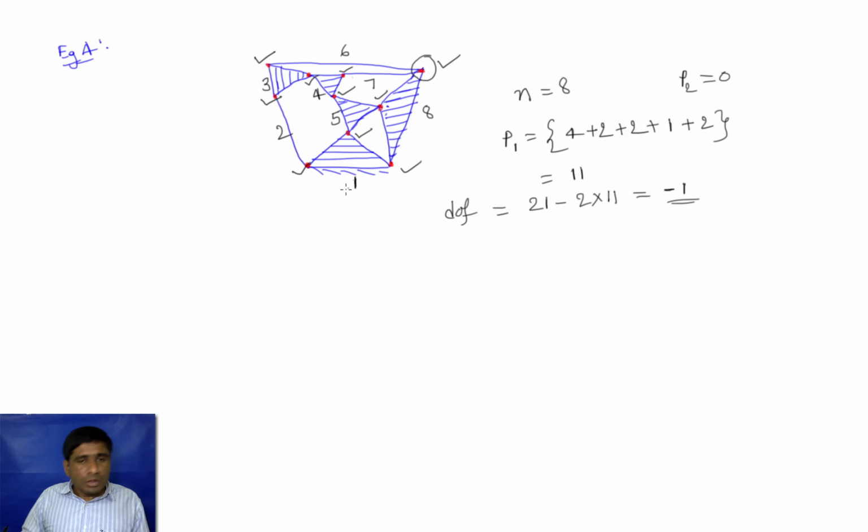So here if you observe, in some cases we are getting degree of freedom positive, and in some cases we are getting 0, and in this particular case we got minus 1. So when degree of freedom is positive, that means the given mechanism has some definite motion for a given input. Or if you want to have a definite output motion, then that many motions should be given to the input link, equivalent to the degree of freedom of that particular mechanism.